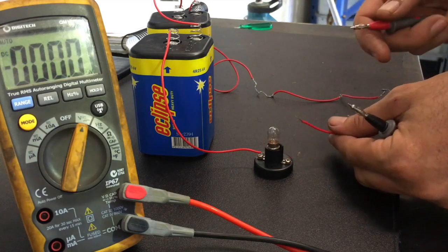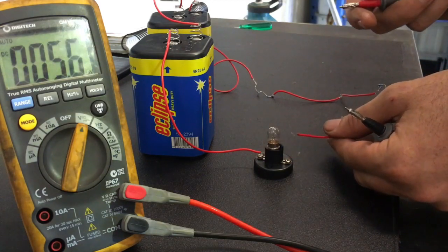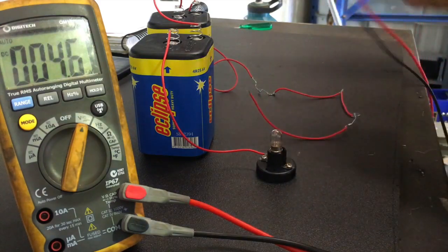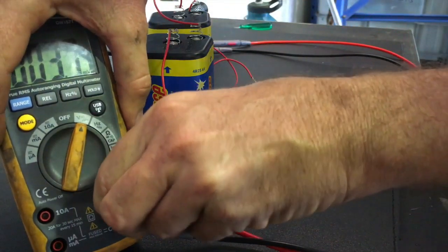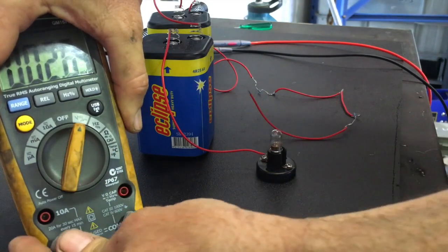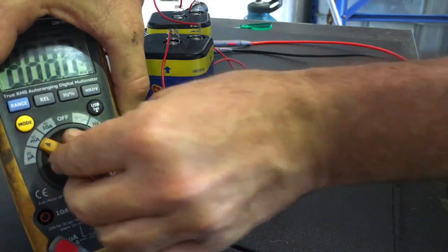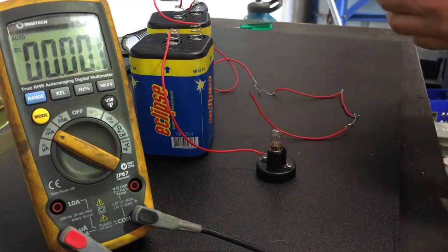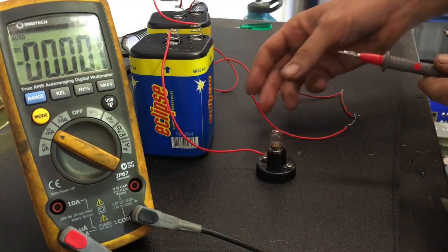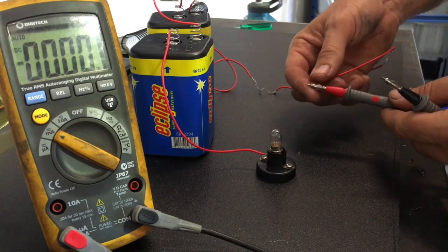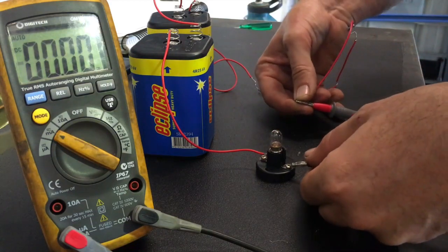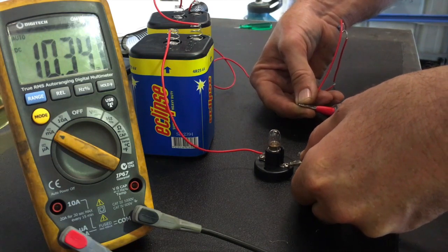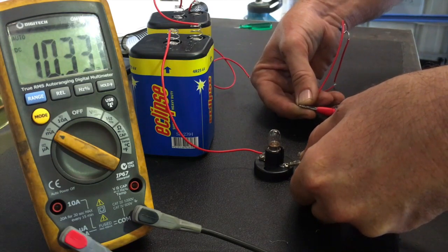Now, one thing you do measure in series is current flow, and so that can be a clue. So what I'll do now is I'll just re-rig this multimeter. I'm going to move my positive lead down here to my little milliamp socket, and change this to a milliamp scale. So now I'm rigged up for measuring current instead of voltage. And if I come here, and once again I measure in series the same way I did with my voltage, I'll see now that 10.34 milliamps is flowing through this circuit.